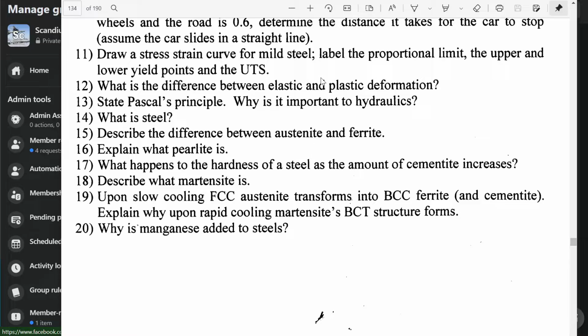Working with metal rulers in our tech rooms, we often have kids who bend them. Not often, but often enough that I think that seems to be a universal concept. So the idea is that while it's still going back to its original shape, that's elastic, whereas once it's bent and it no longer bends back, or even if it has some amount of deformation, that's plastic deformation. Permanent deformation, that's plastic deformation.